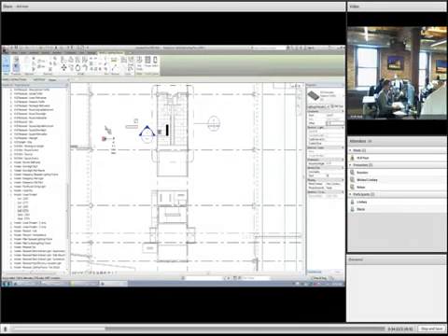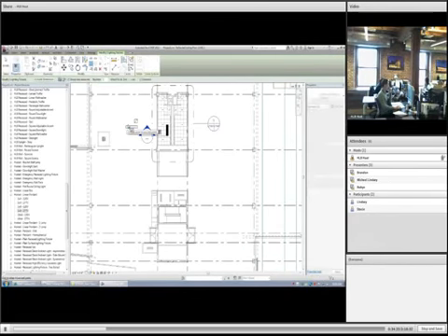The array command is AR, short, or if you like the icons, it is copy, where is it? Array. There it is. So check this out. I can do the AR array command. Okay, this is critical. I'm sure, Michael, you encountered this. The group and associate issue. There are 2 types. First, you have a standard linear array, and then you have a polar array, just like you do in AutoCAD.